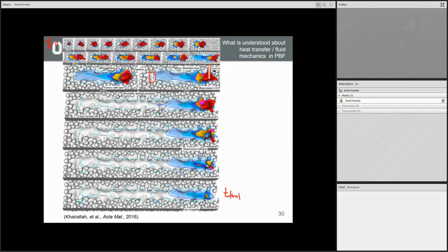again. You see, it's tough to see kind of the stills, but in the videos you saw particles being recruited into the melt pool. So basically you get some sort of migration and they flow into the melt pool. It leaves this area here that actually has a lack of powder, and they call that a denuded zone. So this is an area that was fairly uniformly spread with powder. The melt pool draws the powder in, and now it has a vacancy of powder, actually. So it gets this denuded zone.